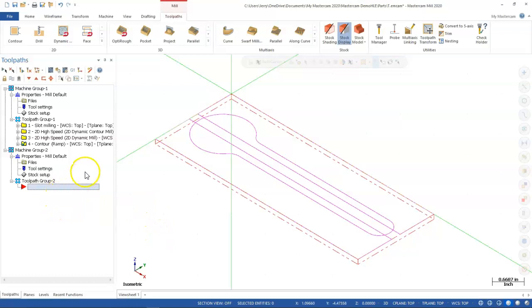And if I wanted to face this, we said this was about 1 inch. So if I had a 3-inch, use my 3-inch facing mill, I can probably get away with just taking 1 pass. If I had the multi-flute and steel, so a 3-inch with 4, 5, 6 flutes, I should be able to buzz across that without ripping it out of the soft jaws too much. Depends on how aggressive we get.